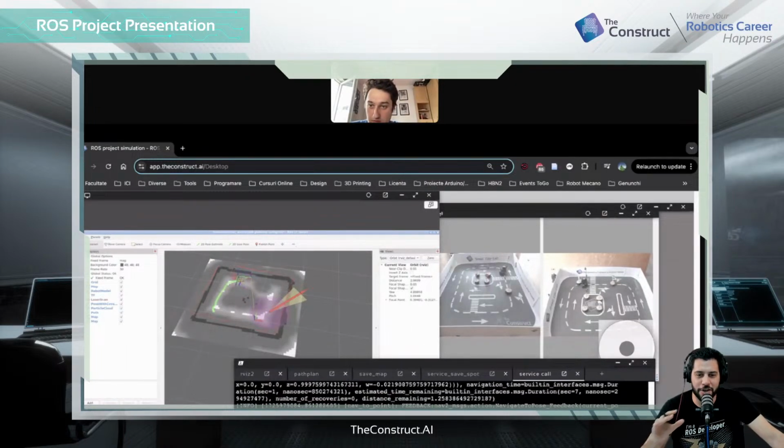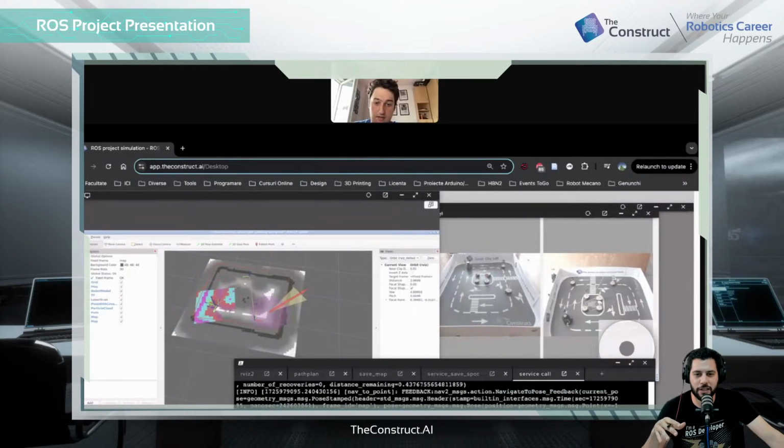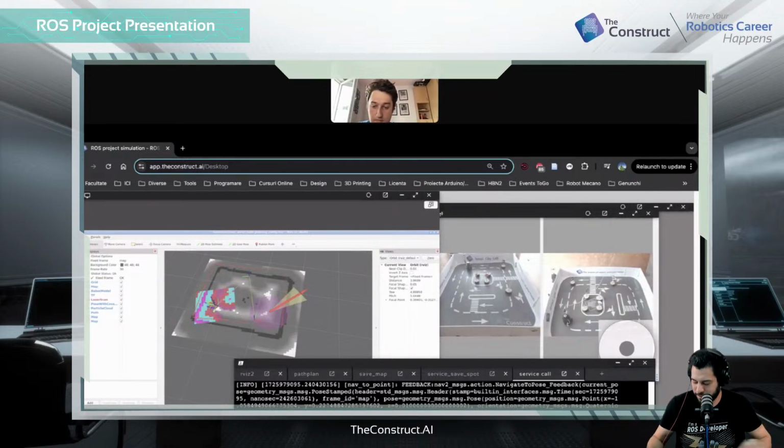Awesome. And this last node is a client then that is reading that YAML file? Yes, it's reading, 1 second. So it gets the spot, the label that I want to search for in this file, in spots2nav.yaml. And you load it as a parameter. That's why when you did start, we had the name of the node and then the ros__parameters, right, in the YAML. Yes. Okay, nice. That's cool.